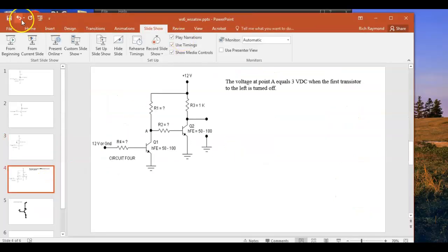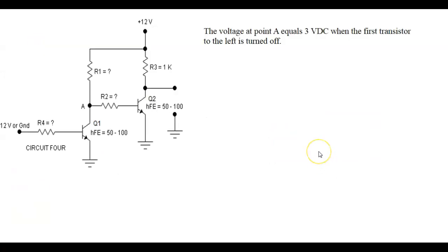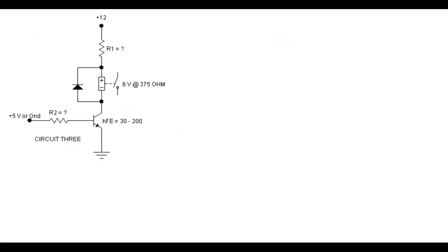Okay, this one. These are the calculations, with the 60. That's 6 volts. Instead of 5.9, I'm doing it at 6 volts on the IC saturated, coming up with an even 16 milliamps.